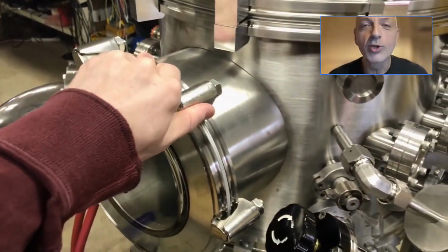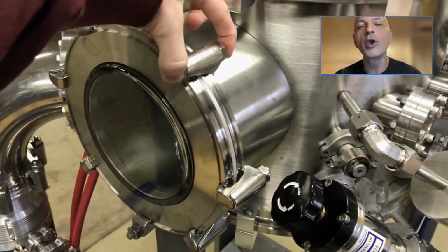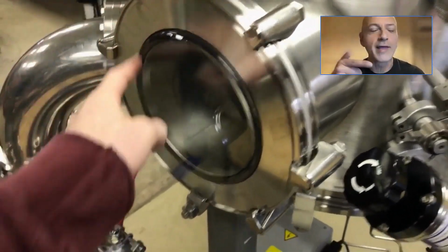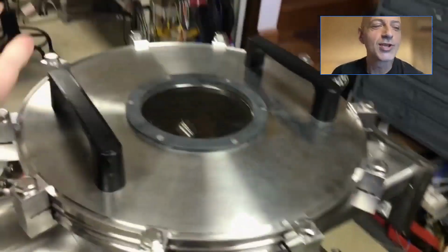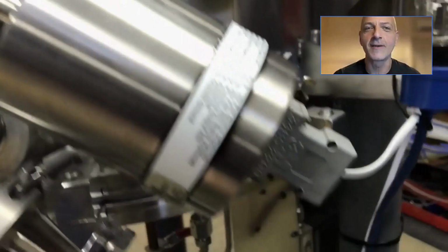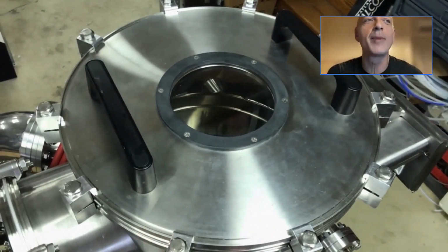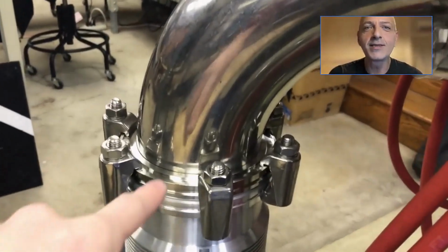The way we trace them is we pull the vacuum, and then we go around the chamber with either soap water or another gas that is different to air, and we try to see what makes a difference in the vacuum. It's a bit hard to find those holes because they are not even visible. When we are talking about seeing the holes visibly with the eyes, it is a joke.